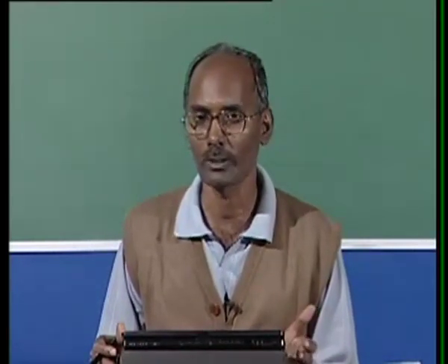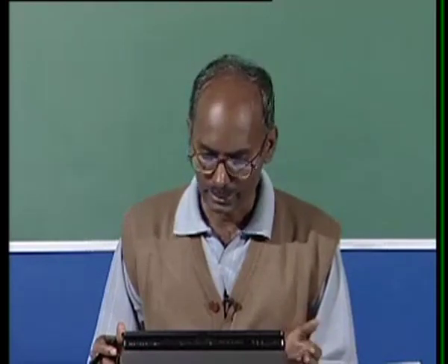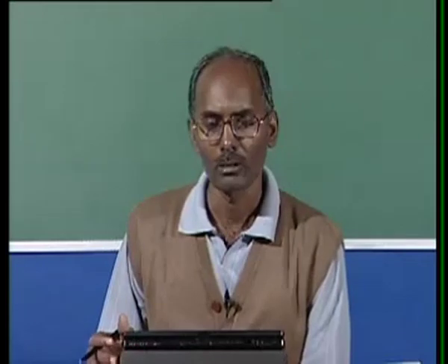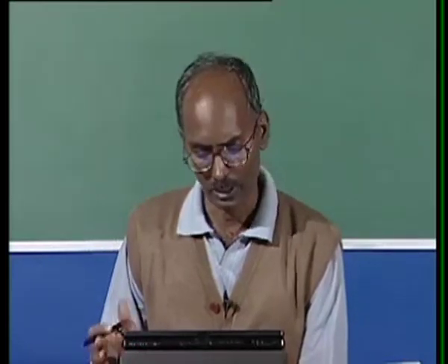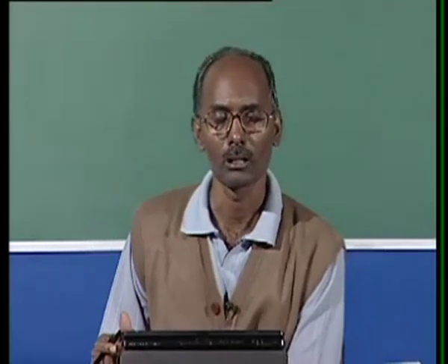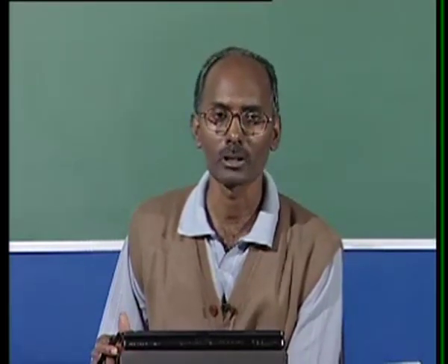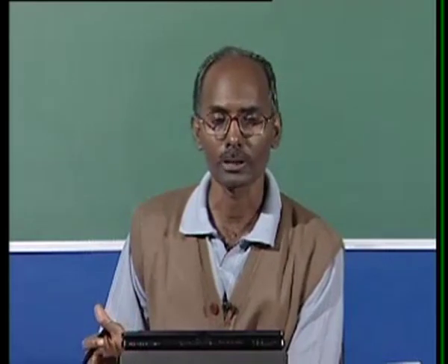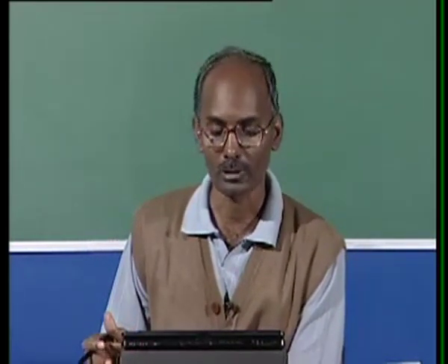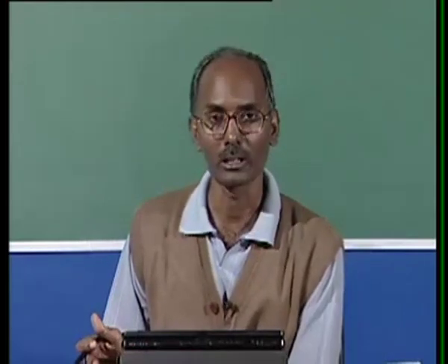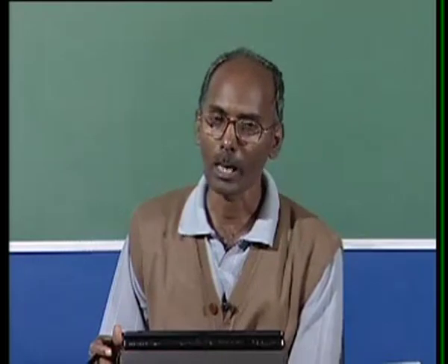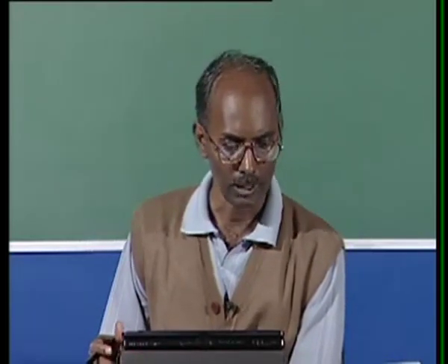For the two area case we saw that we decided Ki1 and Ki2, and based on that we tried to reduce the error. But sometimes the selection of Ki's is not optimal and the system may end up with unstable control. So if you want to reduce the error, sometimes your system may be unstable. That is a major hurdle. So what we have to do is design the optimal load frequency control of the AGC.